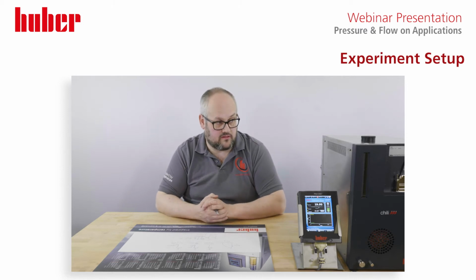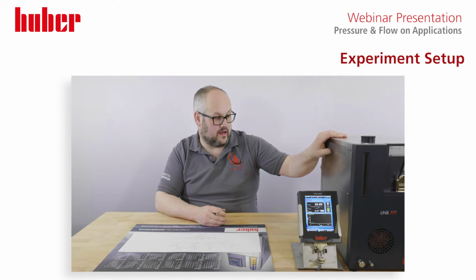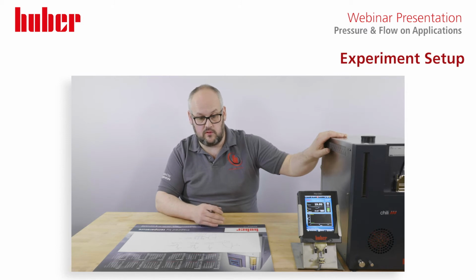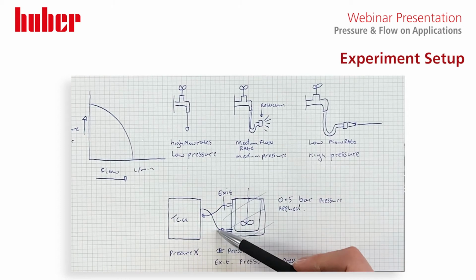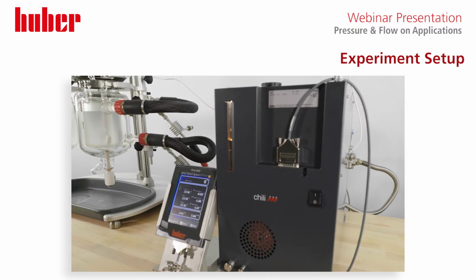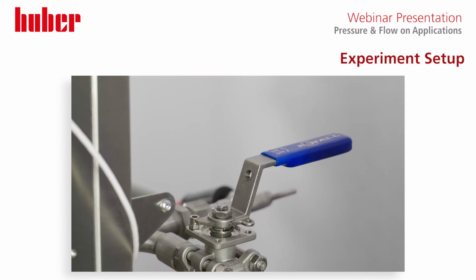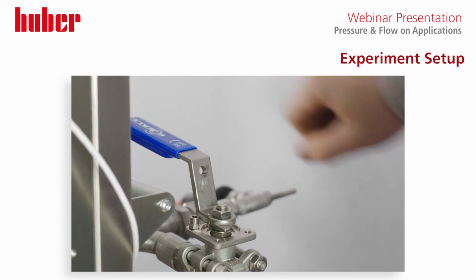So looking at our Unistats, what I've decided to do today was bring our Chili in. It's our smallest Unistat. It has a 0.9 bar pump and it operates at 0 to 45 liters per minute flow rate. So to test the principle of pressure on a reaction system and where we actually see our pressure drop on the system, we've hooked up our Chili to our Radleys reactor system. We've fitted a bypass manifold onto the back of the Chili. So we can see if we bypass some of the fluid, will that have a dramatic effect on the pressure seen by the application?